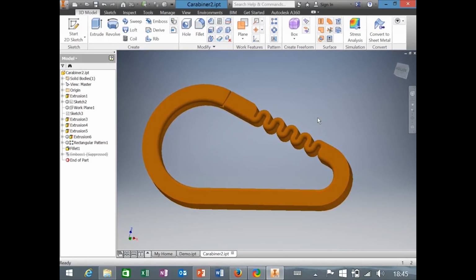And so what we do is we distribute the bending of the plastic over this little squiggly. The squiggle has lots of curves in it. So when you bend that squiggle, the bend is distributed amongst all of those little curves. Each curve will only bend a few degrees, but the total bend will be on the order of 20 or 30 degrees. It is meant to open. I printed it a little bit too small, so the tolerance on the opening is a little bit too tight, so it fused together. If we had a pair of pliers, we could probably pry it apart.